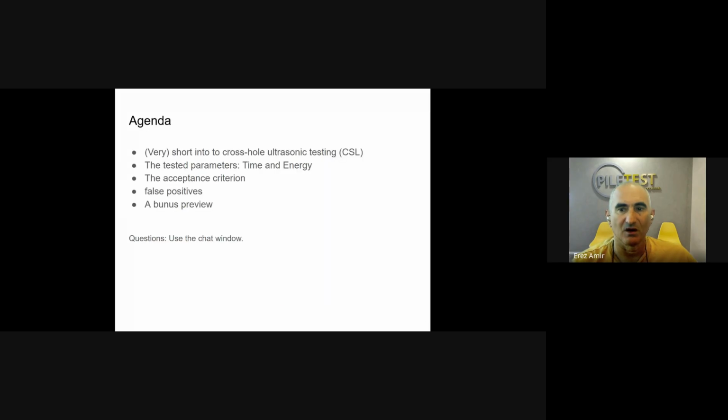And let's talk really quickly about what we're going to talk about today. I'm going to give a very short intro to crosshole ultrasonic testing, which is dubbed CSL, crosshole sonic logging. And then we're going to talk about which parameters the system is actually measuring, which are time and energy, how they are combined into an acceptance criterion, actually a single one.